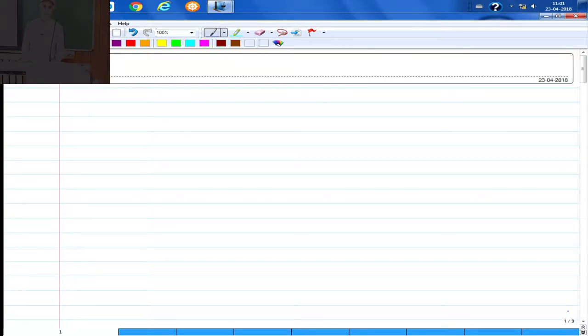So then it depends how you impose these conditions. One of them is the penalty approach, where we add some term into the stiffness matrix, or you use the Lagrange multiplier approach. There are different ways, but ultimately your stiffness matrix basically changes with the imposed contact conditions. Of course we are not doing that in this course. These are topics of an advanced FE course.